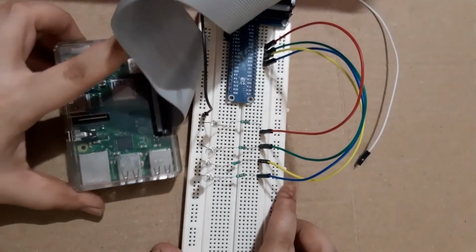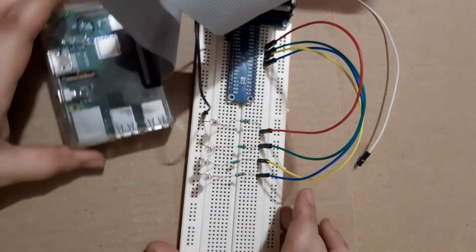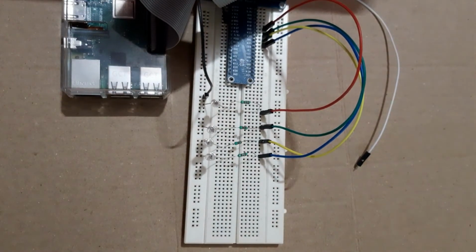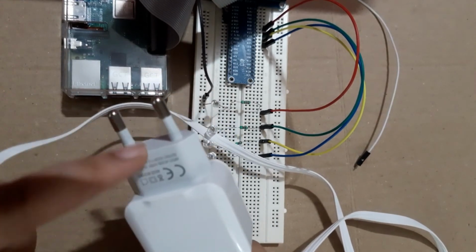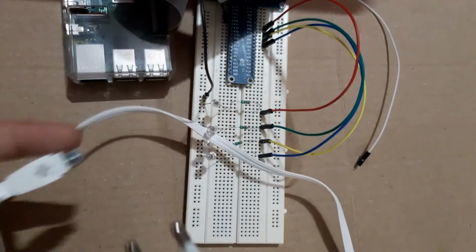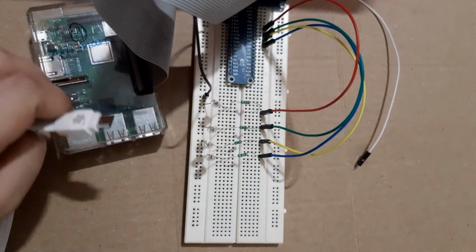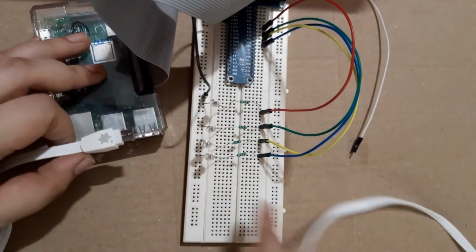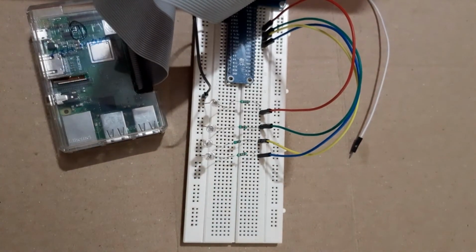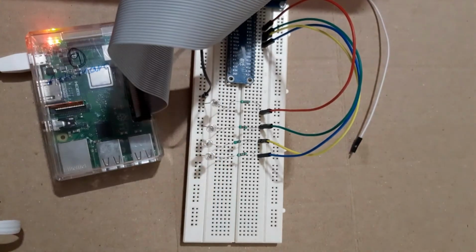Now let us see how it works in terms of the output. These LEDs will glow in some pattern according to the program that we have written. So if I'm going to power up this Raspberry Pi with this USB power supply, I need to connect this end to the 230 volt and this USB connector to the Raspberry Pi. Once I power it up, the Raspberry Pi will start loading the operating system. Since these are the positive voltage pins, they will also pass on the positive voltage to these LEDs, and these LEDs will glow.